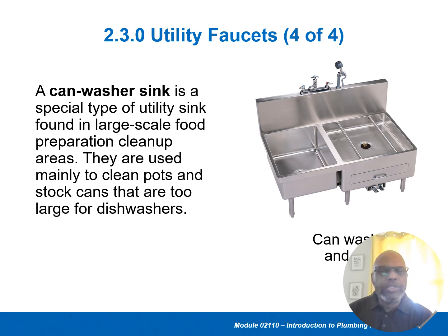In commercial sinks, there are utility faucets, and you can find all different types, with sprayers, with no sprayers, with commercial duty faucets with hot and cold valves on them. They're designed to let a lot of water come out quickly, because these will not have what you call water conservation fittings or restrictors, because in a restaurant you need water and you need it right now.